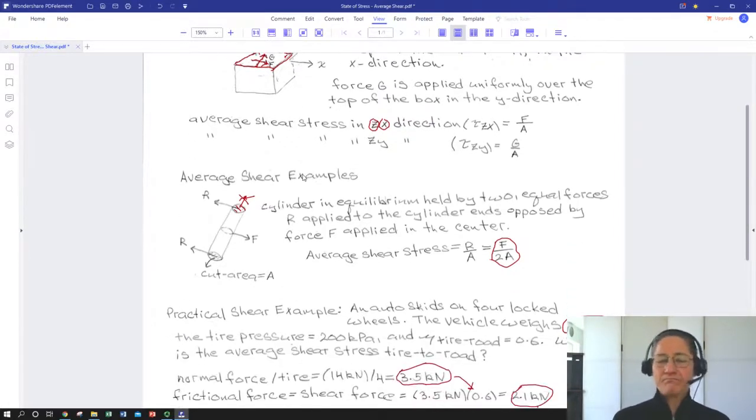And other than that, just remember that we are applying, again, equations of equilibrium. So if we want to relate shear stress for any given loading condition, we have to translate stress to force, equate the forces, and then go back and divide by the applicable area over which it's applied. And if we're yanking at 2 points, we have 2 points at which we're applying that shear force, and so we have to equate that to our other loading.